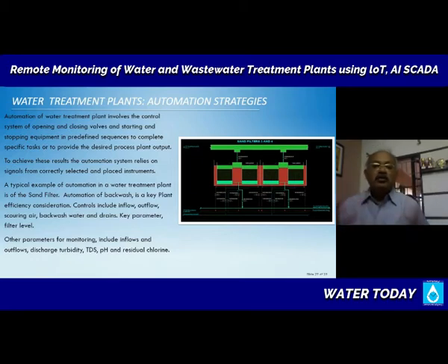Now, if this whole sequence is done manually, it can be a very inefficient system, because either you may backwash the filter too frequently or too infrequently. Both would mean that you are operating under less than optimum production level. So it is possible to see when the level is building up in the sand filter using a simple, for example, ultrasonic level sensing system. And as the level starts to come up because the filter bed is blocked, you start a backwash cycle.